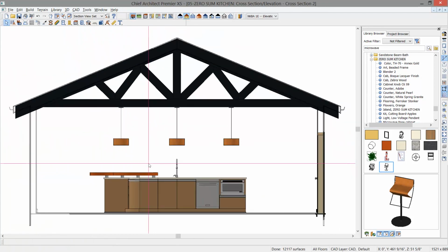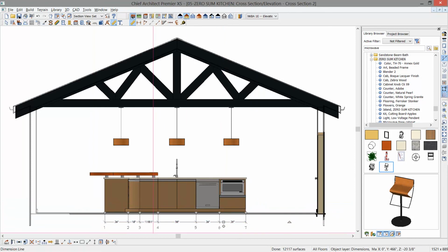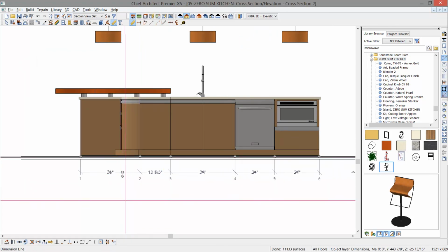And just like in the wall elevation, you can run your dimensions. If you want to run your dimensions through the boxes, you can simply create that dimension line, pull that down, and add your center lines in. If it's picked up dimensions that you don't want, just grab those dimensions and pull those off. It's very easy to set that up.